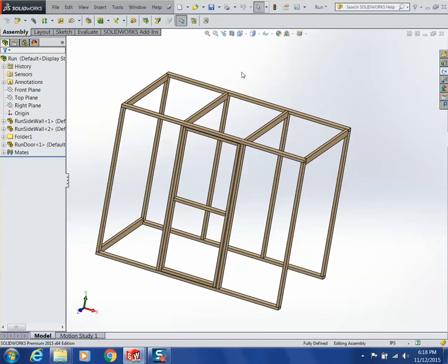Other fun things. How many people are familiar with what this is and have ever used it? Anybody? Okay. This is the shortcut bar that SolidWorks gives you. By default, it shows up under the S key. You can go find it if you need to. This is 100% configurable to whatever you want. If you want to put any commands on here, you can put them on here.